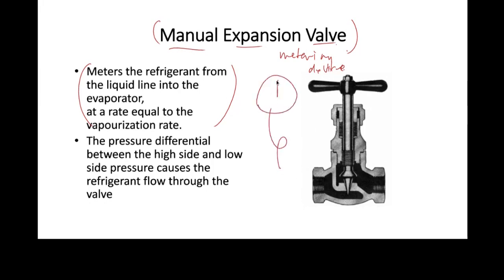And I put a pigtail. It doesn't need a pigtail. It's refrigeration. And so we're going to look at a pressure gauge, and we're going to see, is it at the set point? And then we'll probably adjust it a little bit this way or a little bit that way. And sometimes this is like a vernier valve where we'll have markings, gradations on it, so we know how far it is open or closed or something like that.